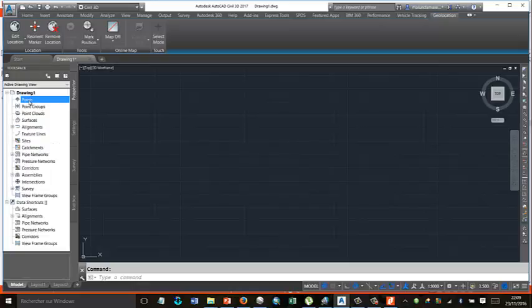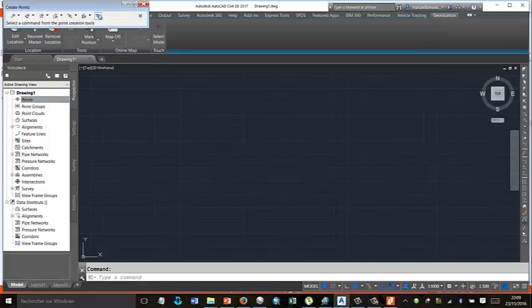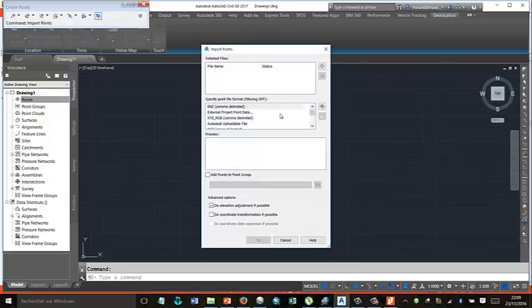With the prospector, I hit the point, right click, create point. I need to create a point. I take just this because I have my text data. I first choose the kind of point that I need. PNEZ means description of the point, east, north, and z, meaning x, y, z, delimited by space.